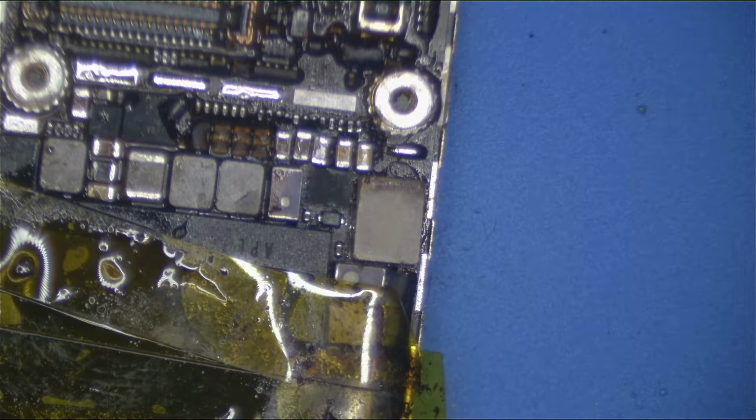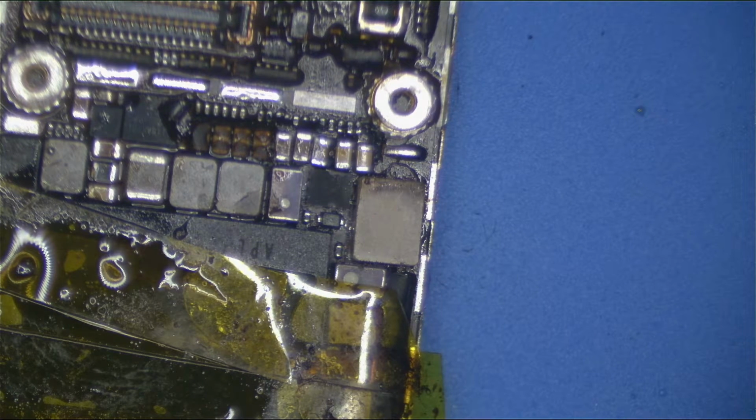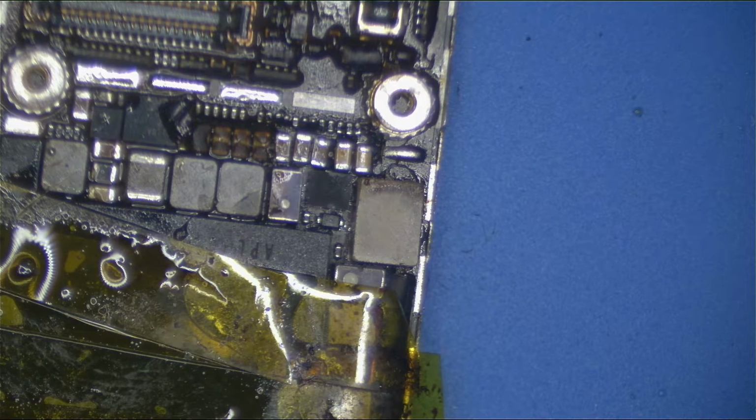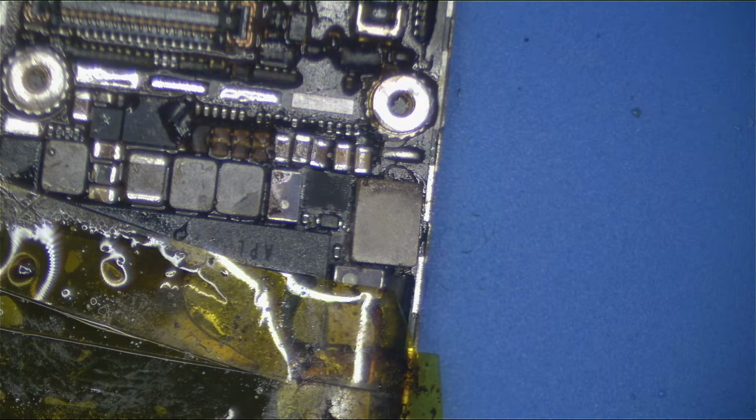When you have solder balls popping out from around the CPU, that's because as you heat it up, the underfill doesn't expand, but the solder below the chips that are underfilled does. All that excess solder that's expanding has to go somewhere, so it'll pop out of the underfill and cause bridging or shorting underneath the CPU. So when you have balls flying out of your CPU, that's how you know you used too much heat, and most likely you're screwed, unless you really want to reball that.